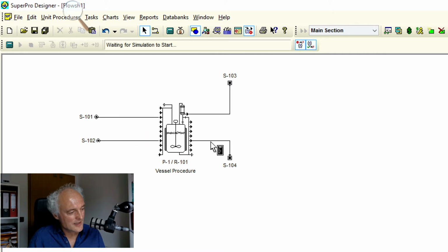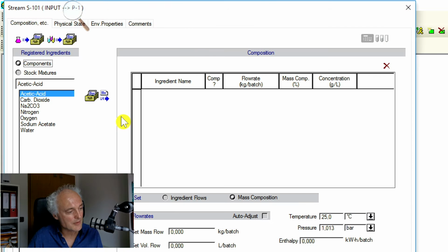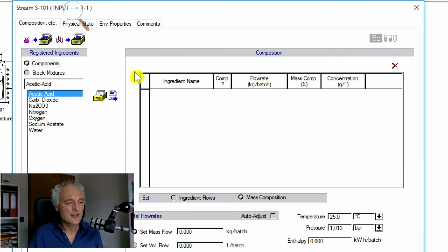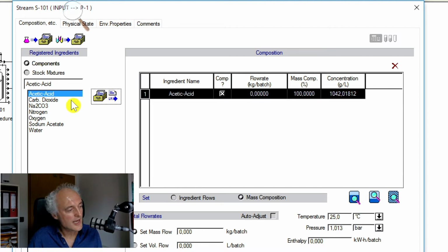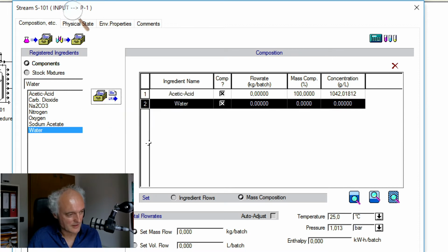Yeah? So now what we have to do is we have to initialize the stream. So what we want to do is we want to initialize the stream 101. So we just double click on the stream. The first stream is our acetic acid stream. So we need to put acetic acid and we need to put, of course, water. So this is what we put here. So now our stream has a composition of 100% acetic acid. This is a lot. And 0% water.